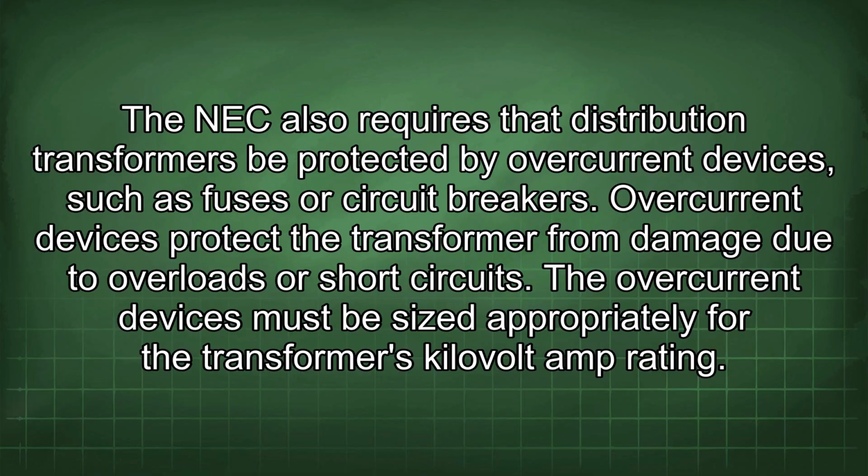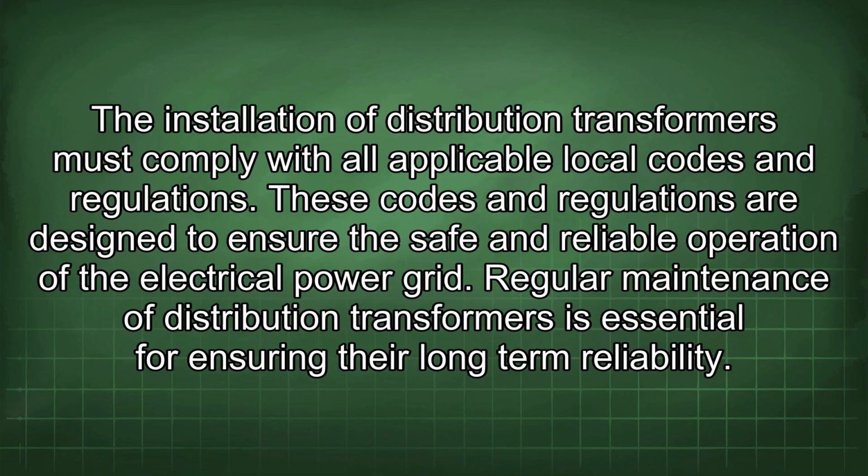The overcurrent devices must be sized appropriately for the transformer's kilovolt amp rating. The installation of distribution transformers must comply with all applicable local codes and regulations. These codes and regulations are designed to ensure the safe and reliable operation of the electrical power grid.